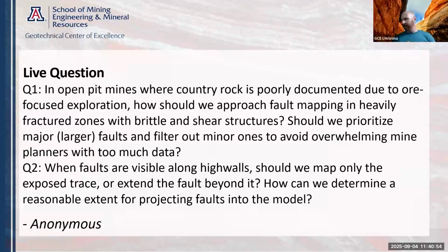Yeah. When faults are visible along a high wall, should we map only the exposed trace or extend the fault beyond it? How can we determine a reasonable extent for projecting faults into the model? Yeah, it's a good question, and you're limited by your data to some extent, but one of the things that I lean towards doing is if you have a bit of a structural understanding of your deposit, what the structural architecture is, and have an idea in your head of the timing relationships and cross-cutting relationships.